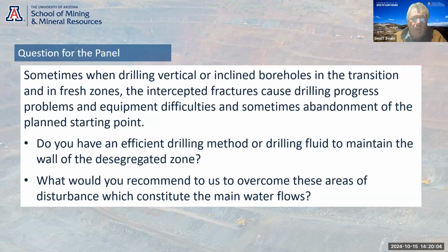Oh yeah, I'll give it a shot to start with. I think the reason back 20, 30 years ago, the reason the dual tube reverse circulation drilling method was kind of pushed was because of unstable holes. And the theory with it, it's obviously an exploration technique. Most holes are drilled 5.25 or 6.5. But the theory is that the drill pipe is a similar size to the bit.